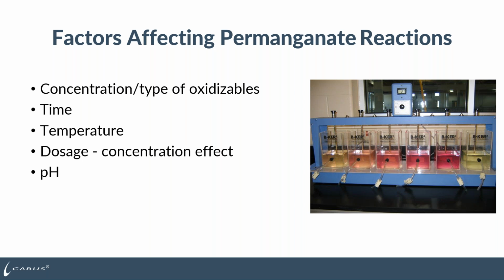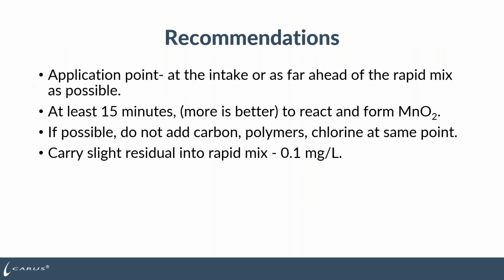What you can see here in the picture is low concentration permanganate kind of looks brown. The raw water, which is all the way on the right, is kind of yellowish to begin with. And then as you increase the permanganate dosage, it starts to take on a pink to purple coloration as you increase the dosage. So visually, you can see what's going on.